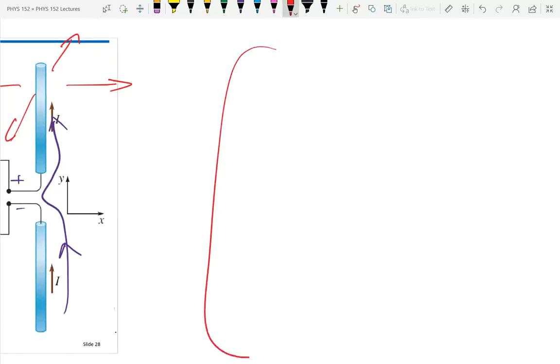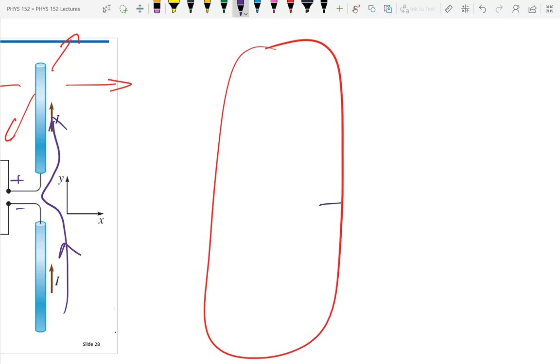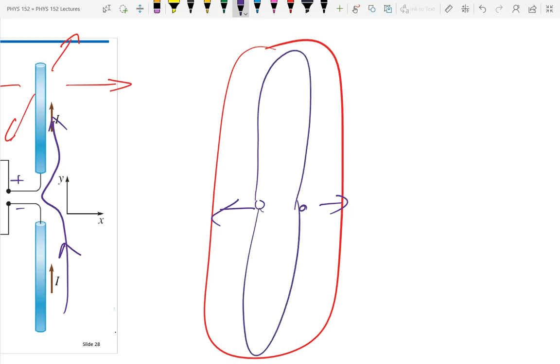You have California Central Valley is like this. Well, you don't want to waste a lot of energy sending your radio signal this way and this way. You're hitting mountains. That's not doing you much good, to spend a lot of your energy hitting mountains. And so if you make your antennae one here and put them in phase, then the biggest part of your signal is broadcast this way. And if your spacing is right, you have no signal being broadcast this way. And so by using multiple towers, they can shape how the signal is going to be broadcast.